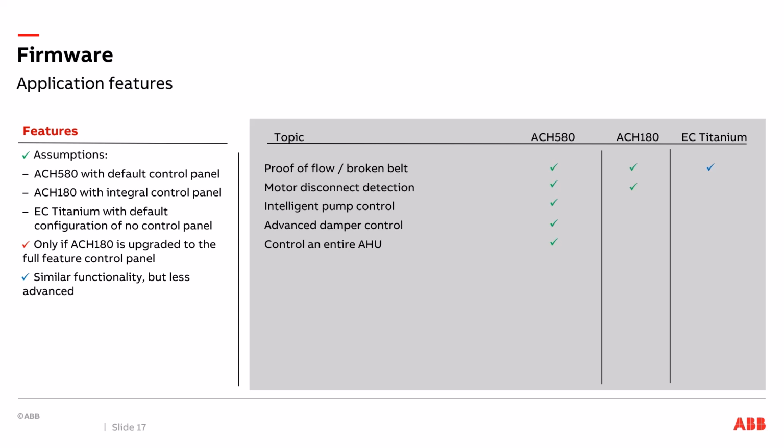You've got intelligent pump control. It's a feature in the ACH580 that allows me to have multiple drives talk to each other, say on a pump skid application, and turn drives on and off as needed for the system to operate and maintain pressure. That's only an ACH580 feature.